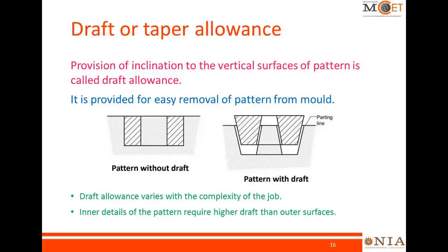And you can see here draft allowance varies with complexity of the job. It depends on how complex the component is, and inner details of the pattern require higher draft than outer surfaces.